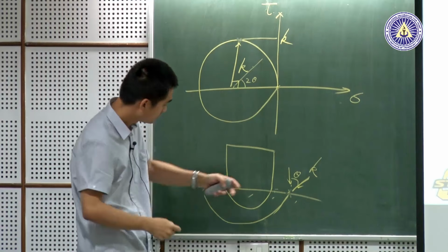Then this blue line I drew is not randomly drawn. This is based on certain plasticity theory, which I'm not going to talk about in detail, but those are called slip lines. Basically, there are 2 types of slip lines in any deformation region. We call one the alpha line, here's the alpha line, and orthogonal to that are the beta lines.